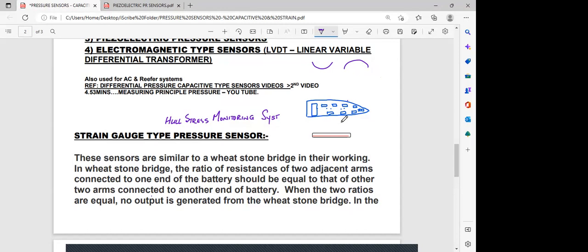movement of the ship. Now, the bending movement of the ship, hogging and sagging, is detected by this particular thing. Although this is a solid stainless steel rod, this solid stainless steel rod bends in sympathy with the ship. And through that particular Wheatstone bridge having this strain gauge, the signal is transmitted to the bridge. The main unit is on the bridge. And then you have a screen showing you what is the strain that your hull is going through at this position, and at all the sensors that are there.